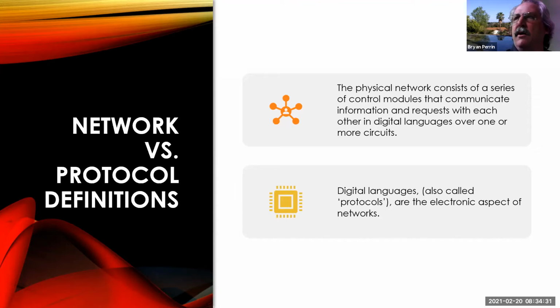So it's important as we talk, and I don't care if it's class 2 or ISO 9141 or any of the other protocols, we have the language, but then how's the network built? The language is important because if I'm going to put a scope on it, I need to know what language is being spoken. I don't need to understand the language, but I need to be able to recognize it. And everyone in this room recognizes languages they don't speak, but yet they're able to recognize it as that language.